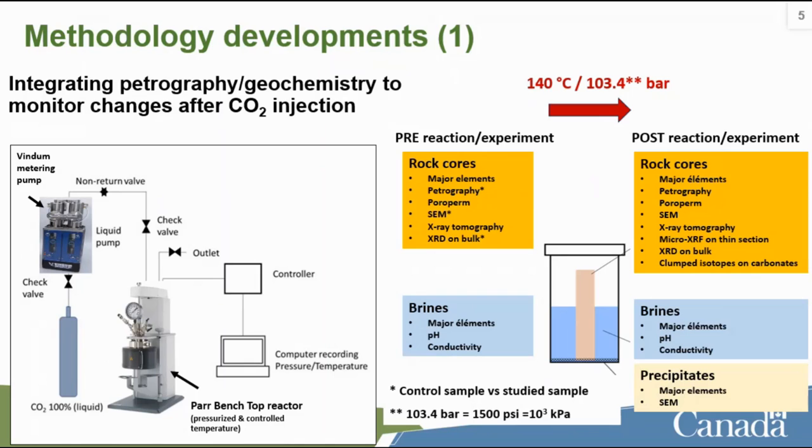So now for some of the results, or maybe I should call them what we managed to achieve in the time frame. The first methodology development, as I said, was to choose the reactor setup. This is a reactor where our INRS partner, César Pasquier, is used to making carbonation experiments. And we use that reactor, we fill it with CO2. After a series of trials and errors, we managed to reach the pressure and temperature conditions we wanted using liquid CO2. This was already something that we had to learn.